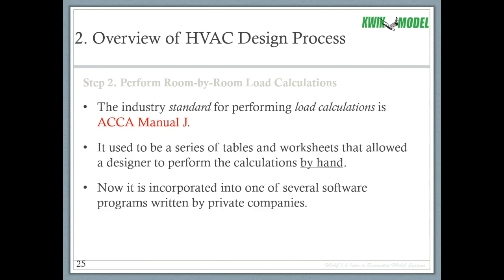You can do a load calculation, and then the really cool thing is you can go in and change something. You can say, okay, what happens to the load calcs if I change the window? If I go from clear windows to low E windows, how much does that affect the load calculations? And you can do that very quickly and very accurately. The problem with using computers and software, if you've heard the expression garbage in, garbage out, is that if you don't do a good job entering the information, it'll do a very precise, very accurate calculation on that garbage, and it will give you garbage right back.